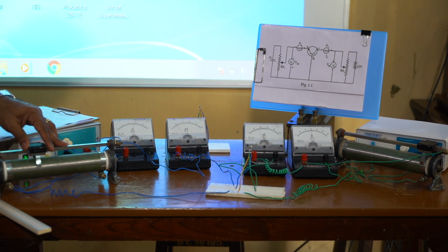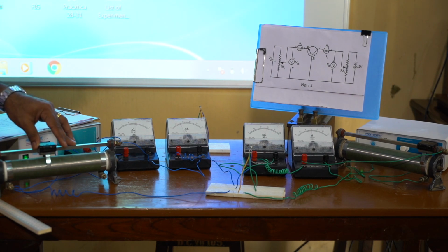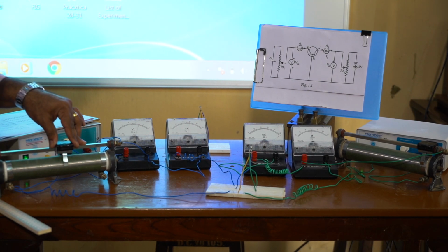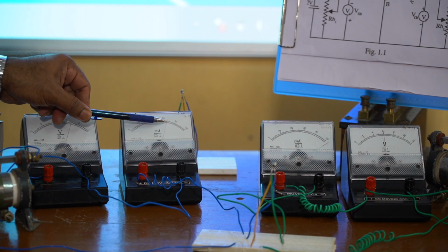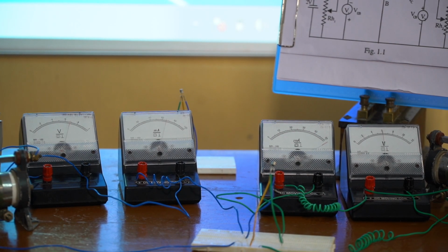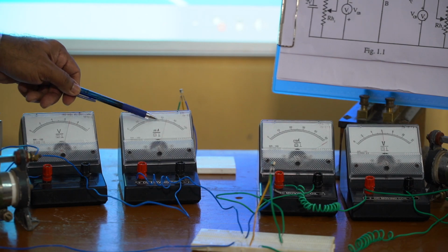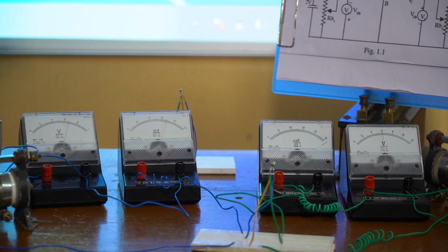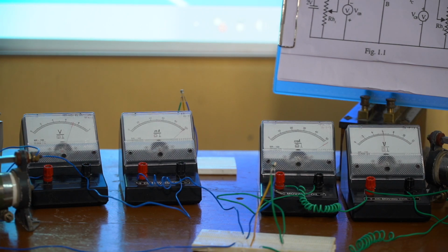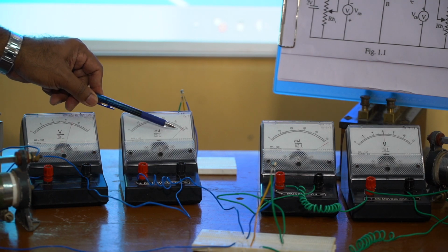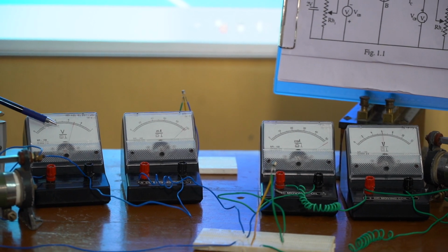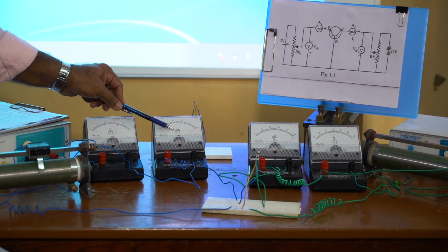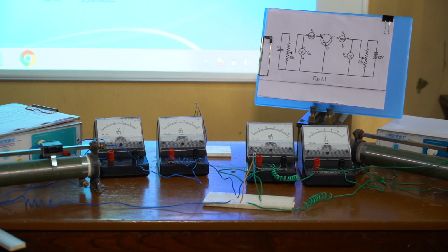Then again we are increasing the value of VEB. Now when VEB is equal to 0.7 or in between we can take readings. When VEB is equal to 0.7 I am getting a current value of say 68 here. So when VEB is equal to 0.7 volt, the IE value is 68. Now again we are changing the value of VEB to say 0.72. For 0.72, we are getting on the milliammeter nearly 100 or 98 milliampere. So with the help of RH1, we change the value of VEB and find out the value of IE at a constant value of VCB.